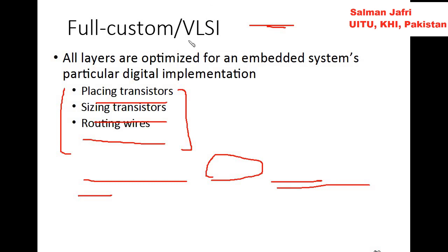So what do we mean by full custom VLSI? All layers are optimized for an embedded system's particular digital implementation. So VLSI is the lowest level design that we can make. So we are responsible for even placing the transistors, for setting the size of the transistors based on power requirements, of course, and we are connecting or routing the wires between these transistors.